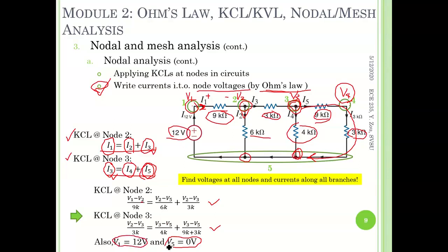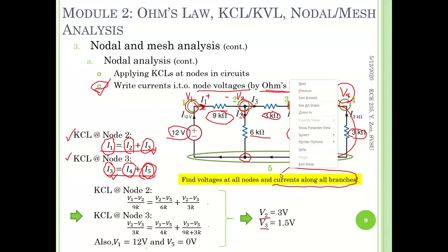So now we basically can consider this scenario as 1, 2, 3, 4, 4 equations and 4 unknowns. We are all set, or say we are ready for algebra calculation. Or you can also consider the scenario as 2 equations, but only 2 unknowns, which are V2 and V3. Anyways, we are ready for algebra calculation. And by some algebra, we are able to come up with the V2 and V3 values, from where we can go further for the current.